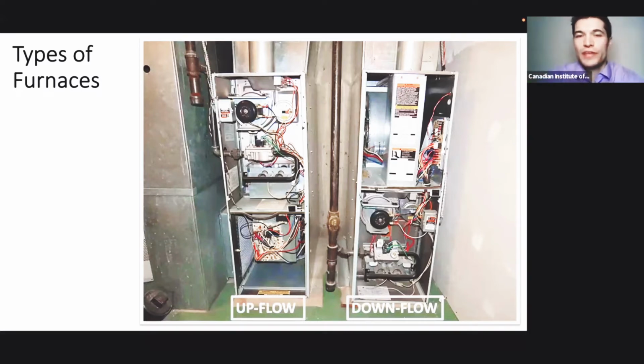So when you take your photos of the furnace, and you take off the upper and lower furnace cabinets, you want to be checking for a few things. First off, you want to see if there's a filter installed, and make sure the filter is actually installed properly. Generally they'll have airflow written on it with an arrow. The easiest way I tell my clients is just make sure the arrow points towards the furnace, because sometimes you may have a different orientation. A lot of times just looking at the furnace size to make sure it's sized accordingly, or the actual state of it. If it's extremely dirty, that will tell you a lot about the maintenance of the house.